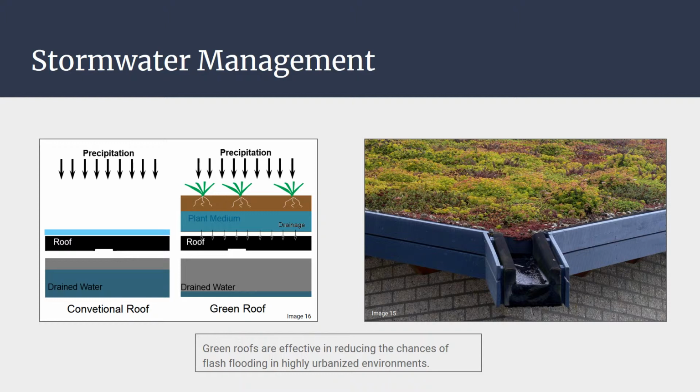When this runoff is causing flooding, it won't become treated, so pollutants such as oil, gas, chemicals, nutrients, and sediment will stay in that runoff water, which could eventually hurt ecosystems, increasing the need for water treatment. During rain events, rain will penetrate the soil of the green roof slowly. This will help slow down the flow rate of runoff and help regulate the flow entering the sewer system, preventing it from reaching maximum capacity.